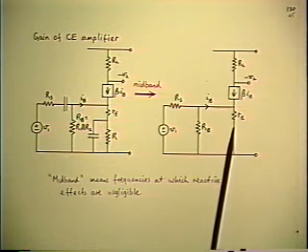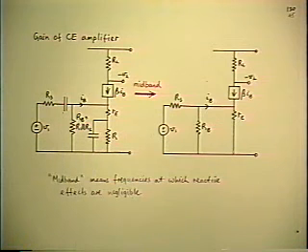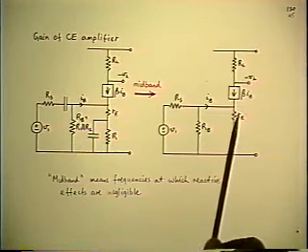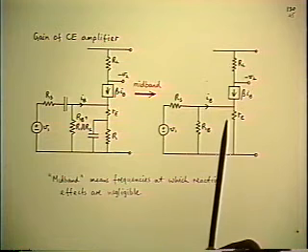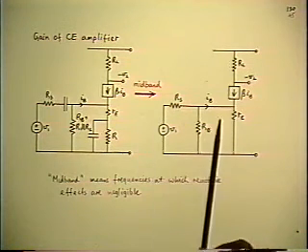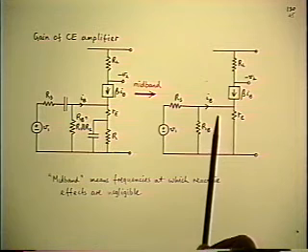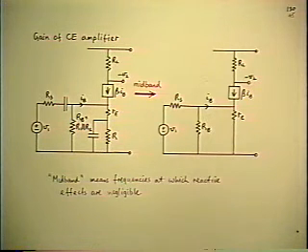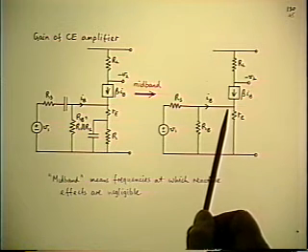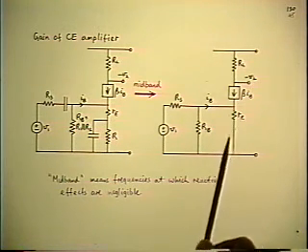That's the small signal AC model, and it's a mid-band model because both the coupling and the bypass capacitors have been taken to be AC shorts. So this is a model valid for frequencies where those two elements are AC shorts. It is still called mid-band because high-frequency capacitors are left out altogether. Principal high-frequency capacitor is the collector base internal junction capacitance of the transistor. Also, there is an internal capacitor known as the diffusion capacitance, which really is across the RE.